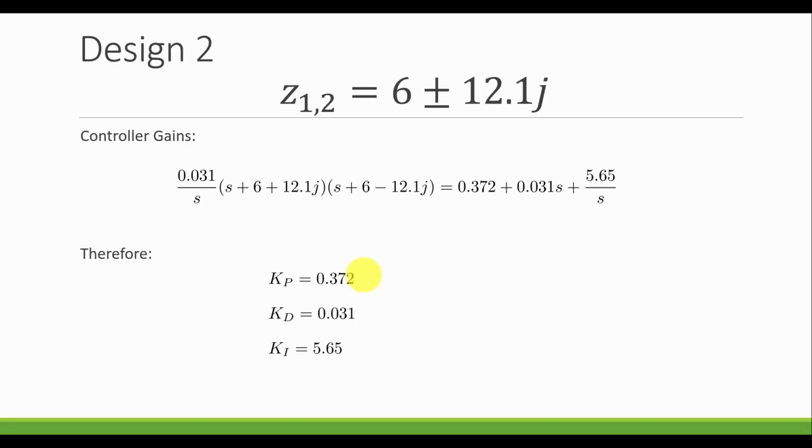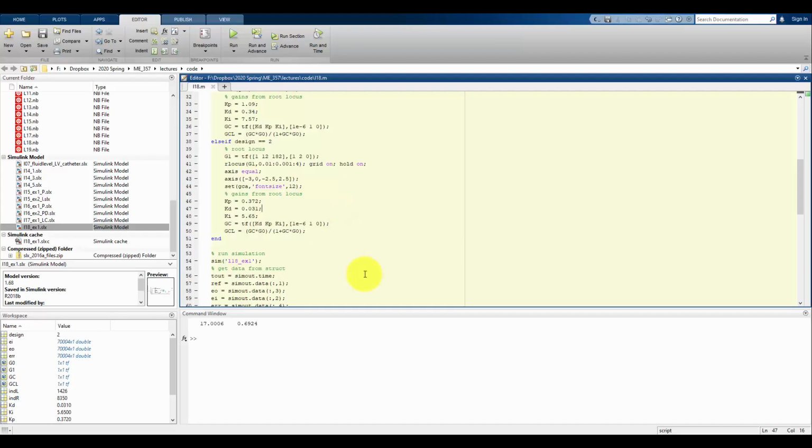And we're going to see at the end that for a PID controller, instead of going through this root-locus method, instead of going through selecting the desired closed-loop poles, there are alternate methods we can use that really jump to the heart of what the PID control is about, these 3 gains, and going directly and changing what these 3 gains are and seeing what the outcome is. But we'll talk about that after this example.